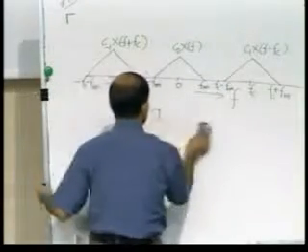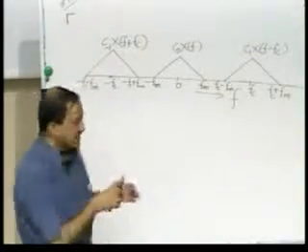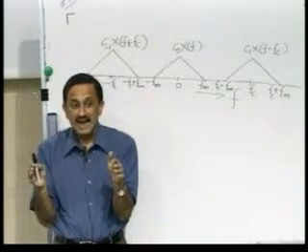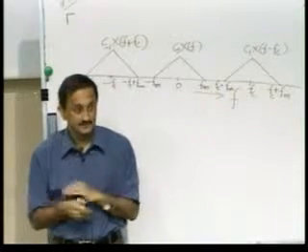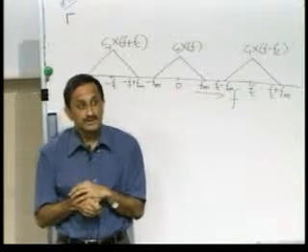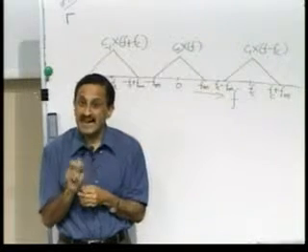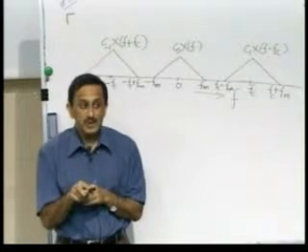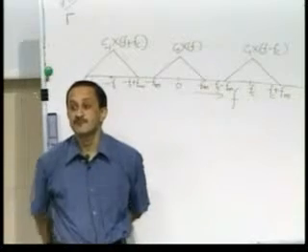So, now coming back to this issue here, what we have done is to take a signal which was originally in a low frequency range, right, and translate it into a high frequency range as a consequence of aliasing. Now, we shall make use of the same idea to see if we can relax the Nyquist principle in a situation where the signal does not occupy the whole band up to its maximum frequency component.